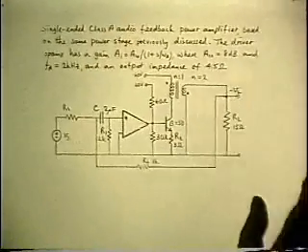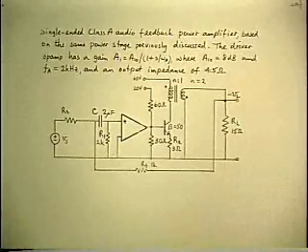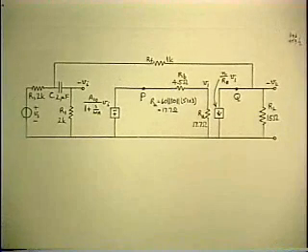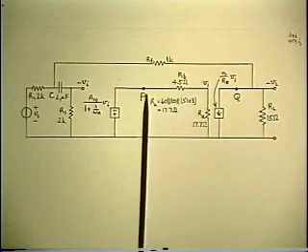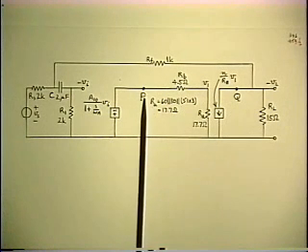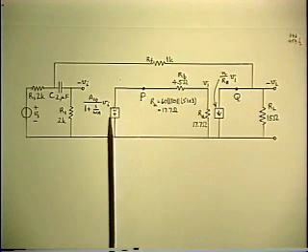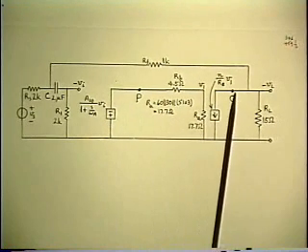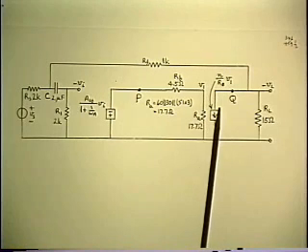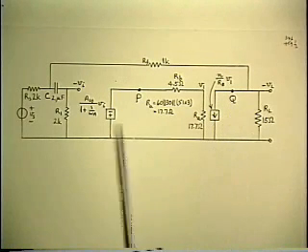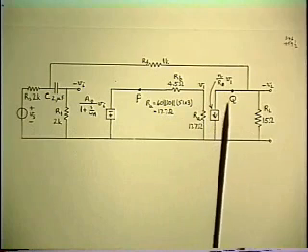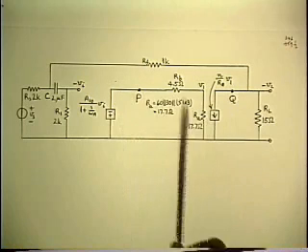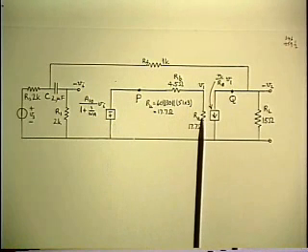Once again, if we go back to this little power amplifier model as an example, this was the first version of the equivalent circuit that we came up with. And we looked at the relative merits of injecting a voltage at point P, where it's in series with an ideal voltage source, which was acceptable, versus injecting at a point Q, where it's an ideal current source, and we did current injection. And I said more or less arbitrarily, let's do current injection, just to illustrate that method, which allows us to get rid of this internal loop and simplify the problem.